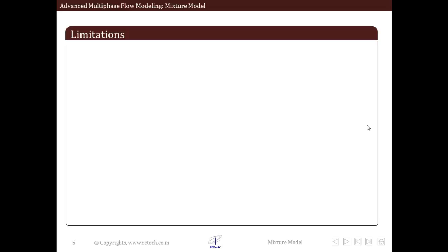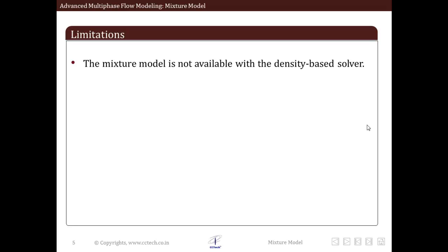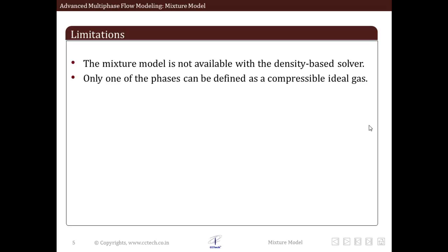Mixture model also comes with its limitations. We will discuss them one by one in this particular slide. The mixture model is not available with the density-based solver. Only one phase of the mixture model can be defined as a compressible ideal gas.